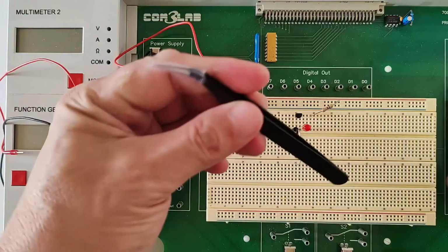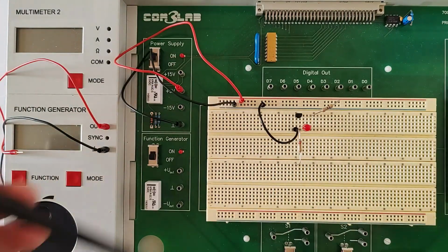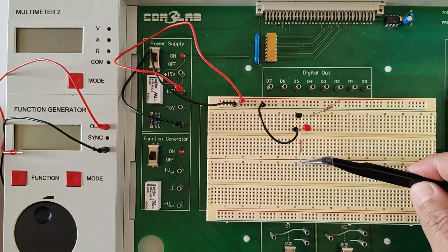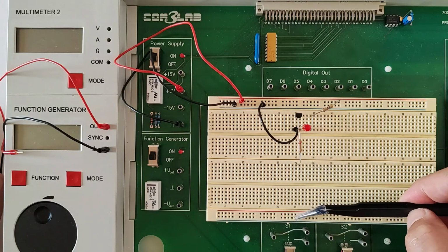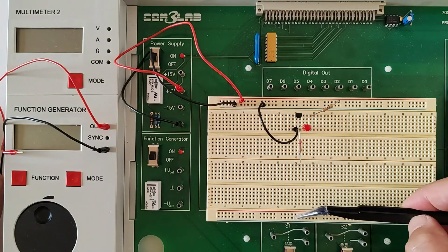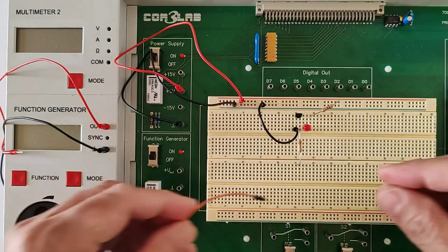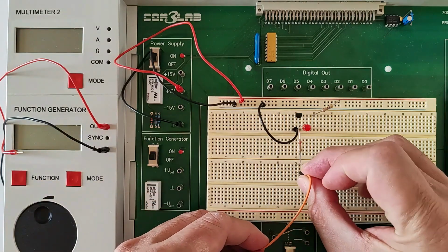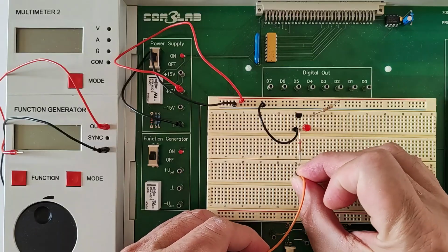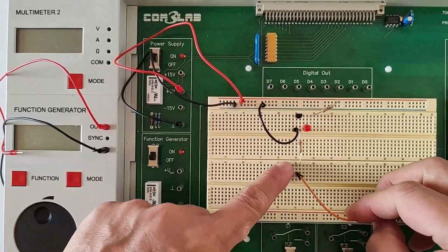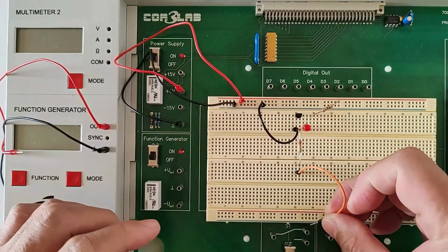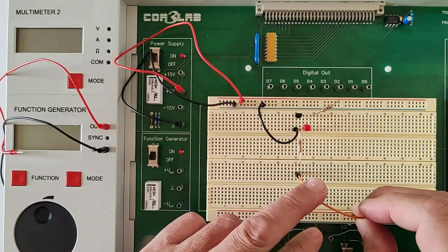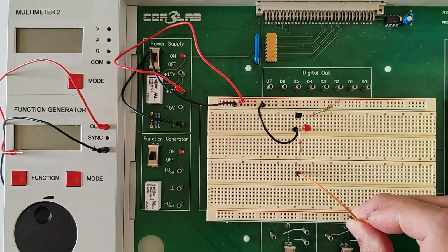The positive terminal of our function generator would need to be connected to the leg of this resistor, the 220 kilo ohm resistor. So what I'll do first, let me first connect a jumper wire from these pins going to the power rail down. I'm going to use the red side of this bottom power rail. So I will need one more jumper cable. I'll connect it here, the same pins where this leg of the 220 kilo ohm resistor is located, and I'm going to connect it to the bottom power rail. I'll use the red side.